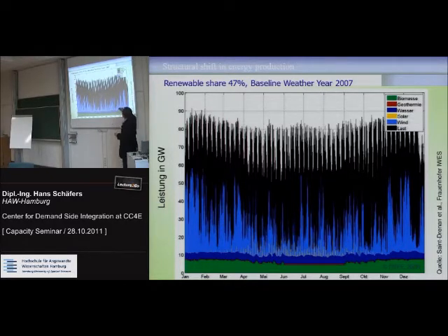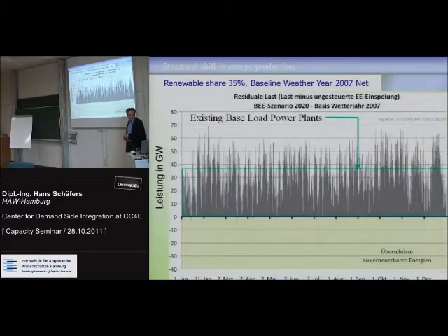Now what you can see is that sometimes columns reach very high. There's only little room left, actually. So what you can do now for every hour is you can subtract all the renewable production from the actual simulated demand. The demand is a bit higher here because what they calculated in is that we are going to use more electricity due to more electricity in the mobility sector that we foresee there in 10 years' time, right? More e-cars, right? So if you subtract all the renewable production from the actual demand, you end up with a graph that looks like this.